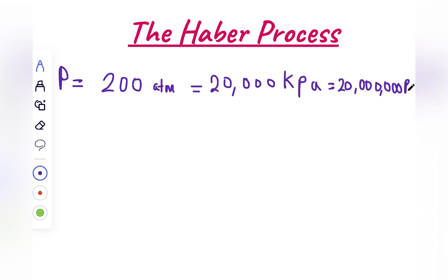Okay, so we are saying the pressure. This is a trade-off, in that the pressure should not be too high. 200 atmosphere is okay. You know, the pressure can be higher, but when you increase the pressure, the yield of ammonia reduces. The yield will decrease. So this is a very vital consideration for this case.